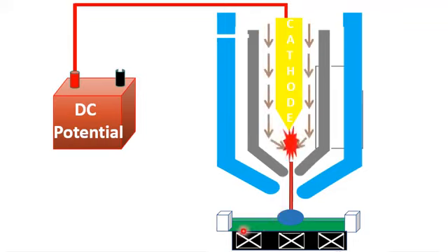The magnetic field lines will interact electromagnetically with the electrons, ions and neutrals, and due to the electromagnetic field in a specific direction, they will confine the plasma to a specific region on the surface of the cathode.